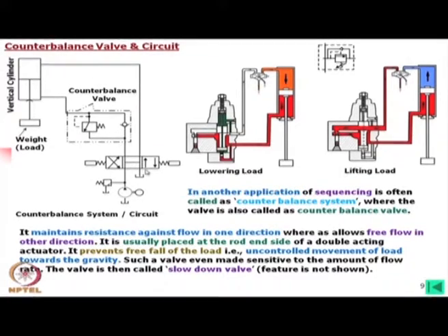So, this side is connected to the tank, and the pump side or pressure side is connected the other way. Now, while this load is being lowered, how much pressure do we need? Practically we do not need the pressure. What we need is the flow, because this is to be filled, otherwise it will not move.